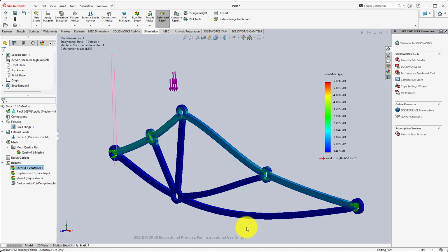But again, I said some of you are going to hold 100, 150 pounds, and we want to make our frames as light as we can and hold as much as we can. I've seen some people with very light frames hold some high loads. So this is hopefully going to help you do some analysis using FEA and give you some cool ways you can design your frame and do on-the-fly calculations with it, just like we would do in industry, because we would do this, and then once we get it to where we want it to be, we can go out and manufacture it.